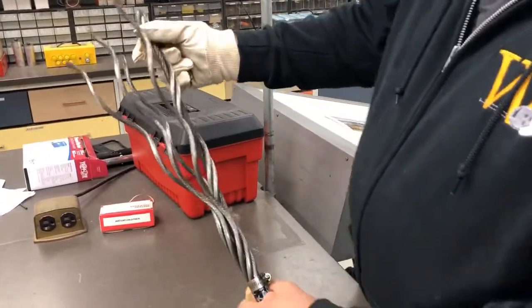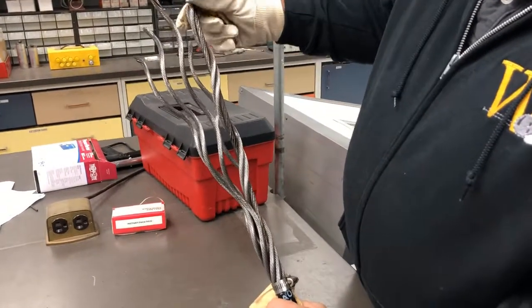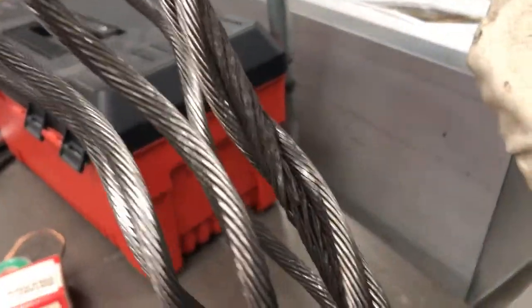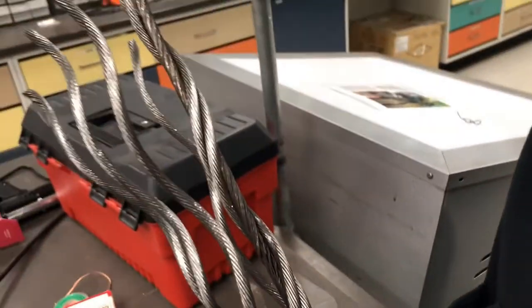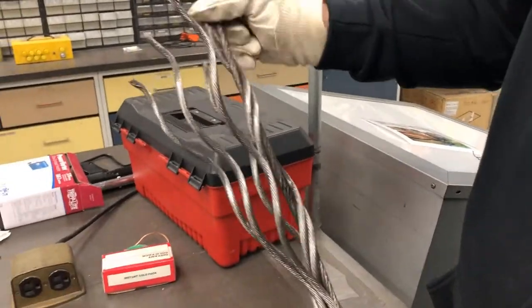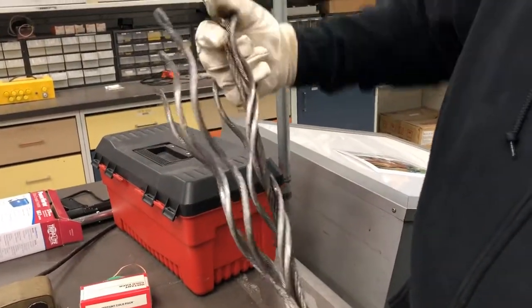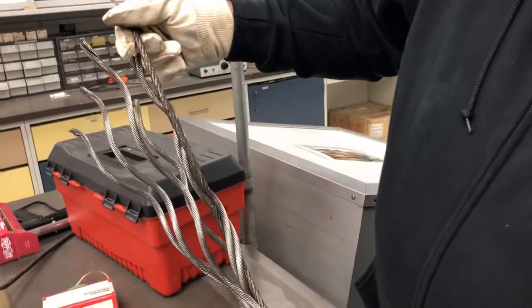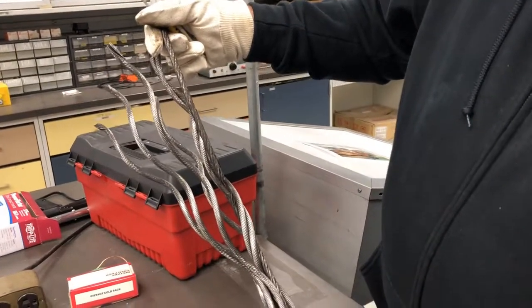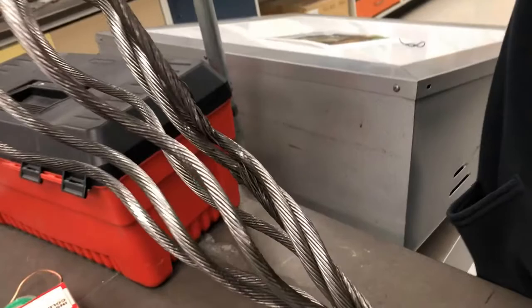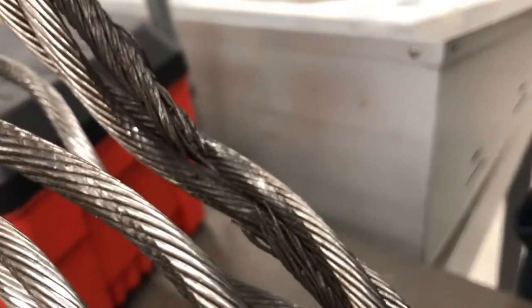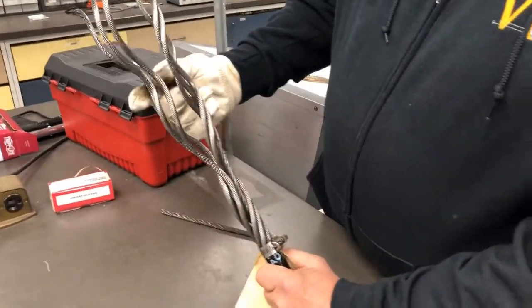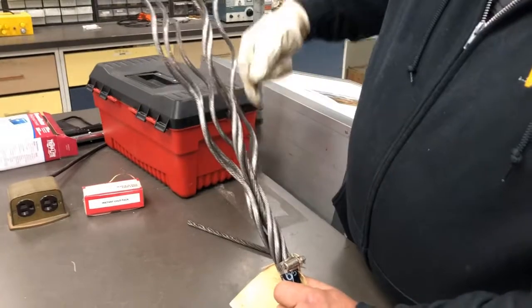We observe the core of the rope where it has failed. And this portion internal to the rope simply comes out. And this is where localized corrosion has deteriorated the rope to the point where it has actually failed the IWRC, because of the loss of core support to the rope.